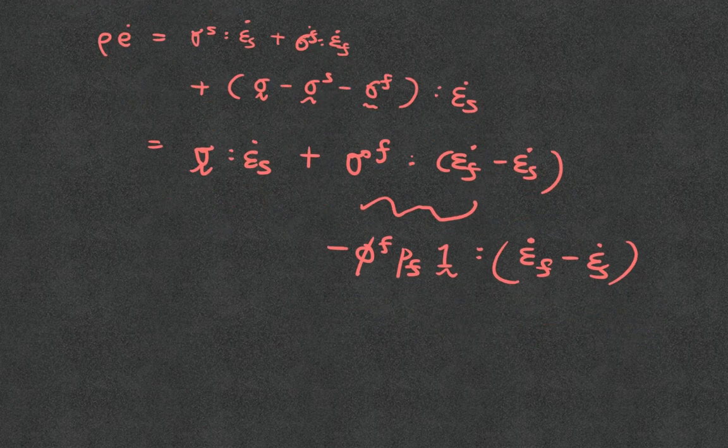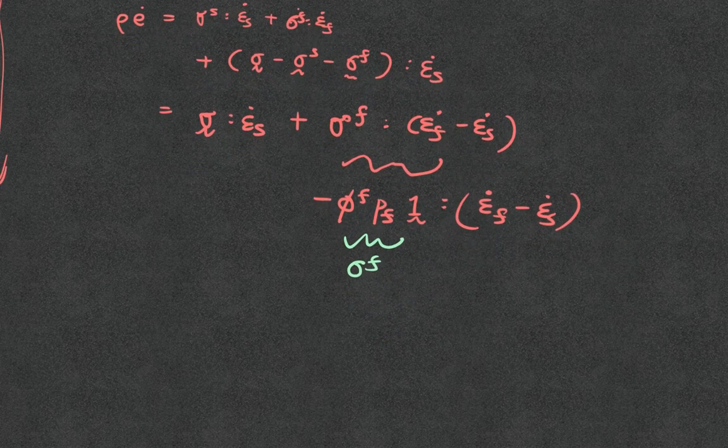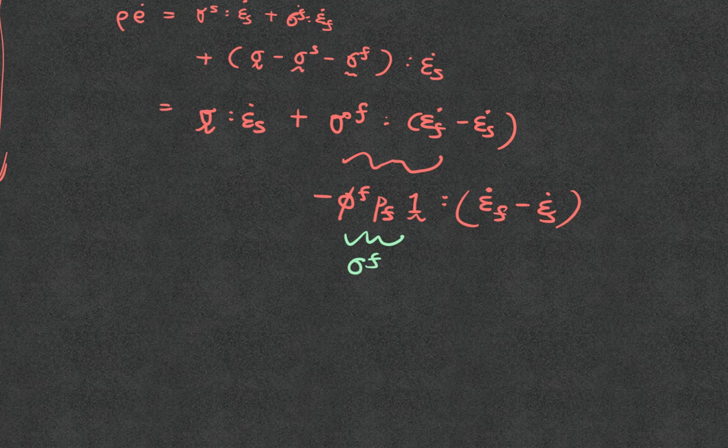Again, this whole term is just the fluid stress. The fluid won't have any shear stress. Does that make sense? If you had shear stress, if you had a shear modulus, then what Bruce Lee said about water taking the shape of its container would not be true, right? So you only have the volumetric, the pressure term, the deviatoric term is 0, and hence you get this term.